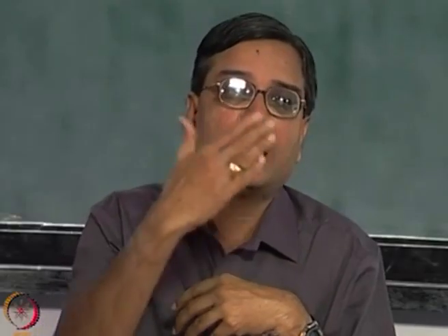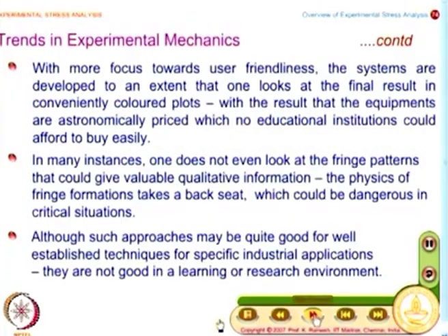Although phase shifting methods are the norm of the day in optical methods, we would focus on the conventional approach of looking at fringes, so that you gain insight into the experimental method as well as improve your understanding of solid mechanics, because many of those things you would have just seen in books as equations, and when you see them as fringe patterns, you also have an appreciation of how the values are at different points on the model. It will also reinforce your understanding of solid mechanics. So, that is what we will look at.